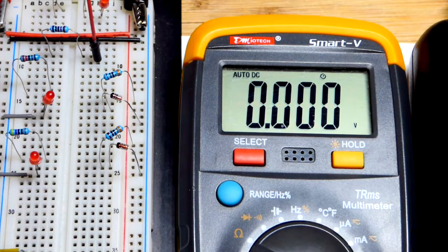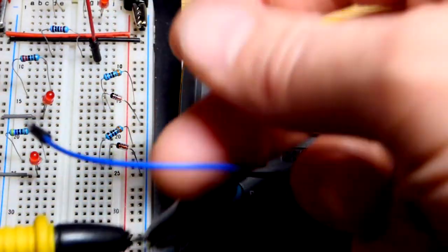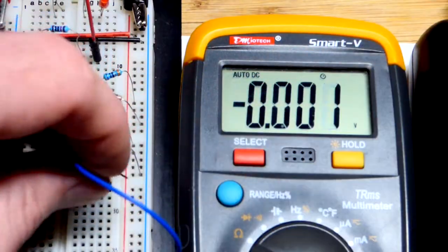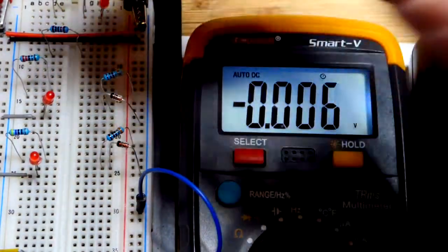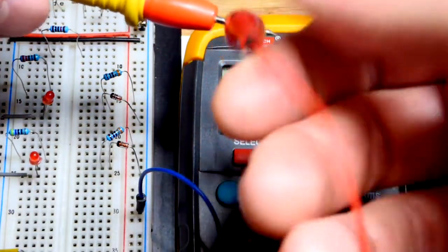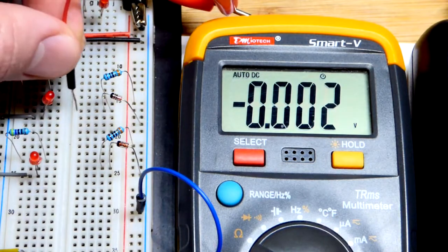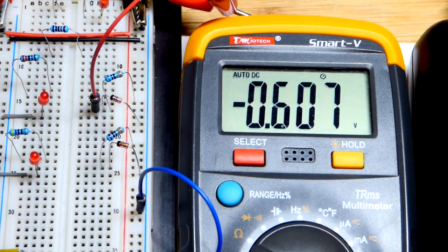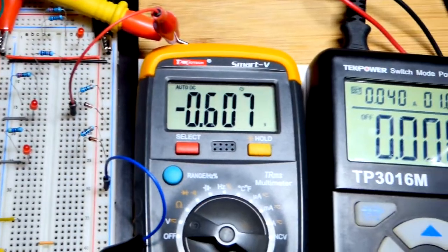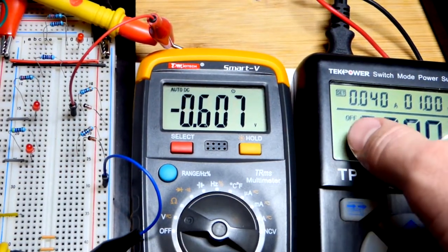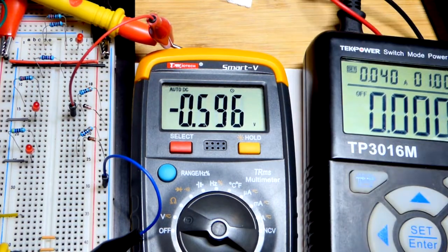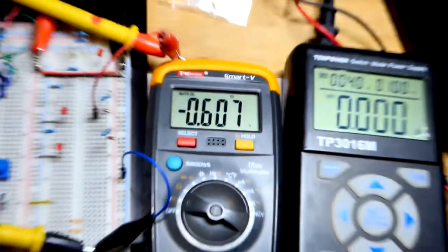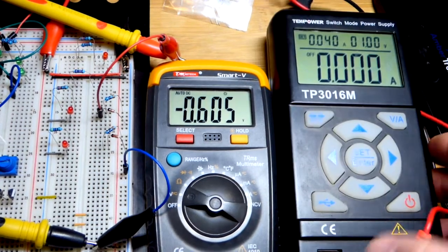So now we got the multimeter. I already have it on, set to measure voltage, and I've gone over this process before: the alligator clips to the probes, so that I can just take the other end of the alligator clips, which I crimped to jumper wires, and plug them onto the board so we can measure the voltage directly. Right now we actually have a negative voltage. That's because this power supply, when the output is off, actually gives a negative voltage. So that's something to be aware of if that'll be a problem.